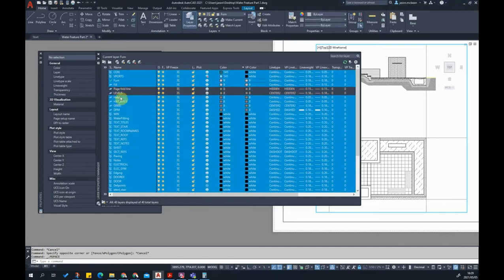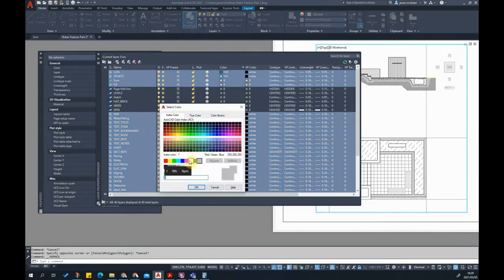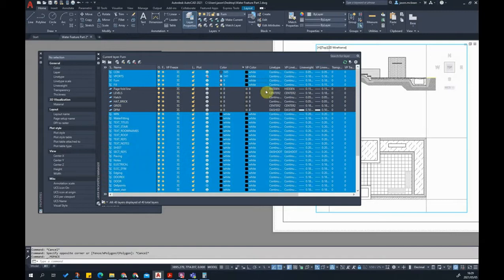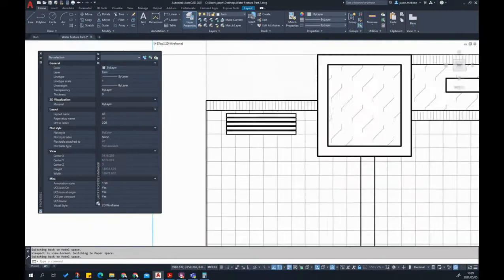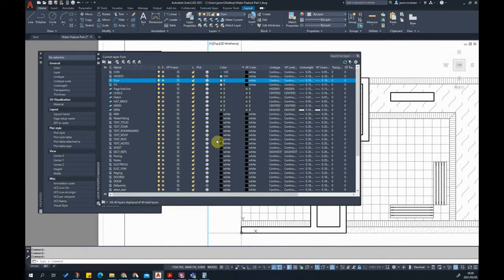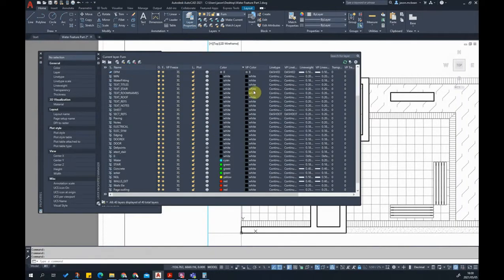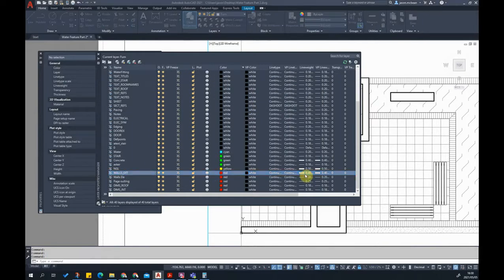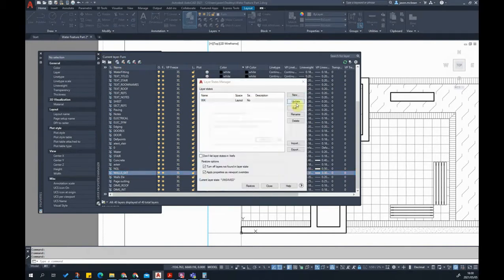The rest of those will be the furniture layer. I'll put it on a darker layer in this instance just because of the way I want it to work. Now I just want to fix my line weights. For now the furniture layer is good. It's just my wall layer. This wall exterior, change that to 0.3. For this I'm going to make it 0.3.